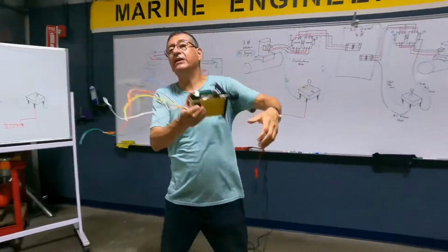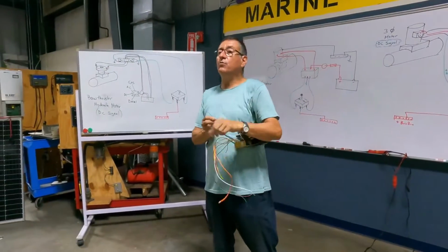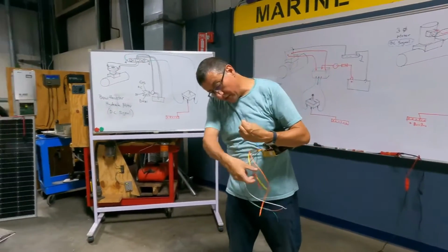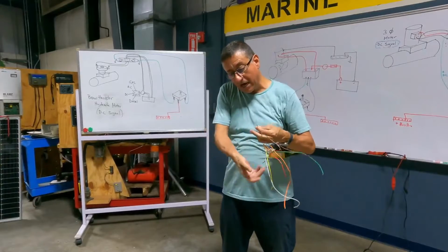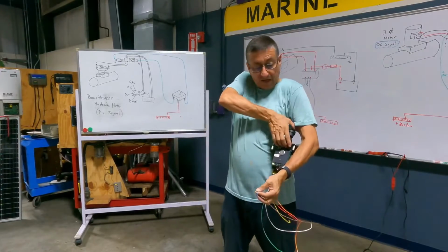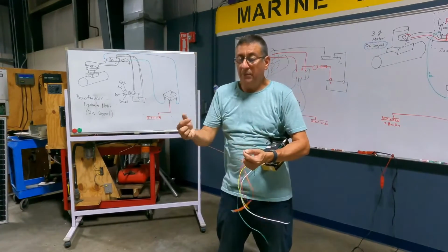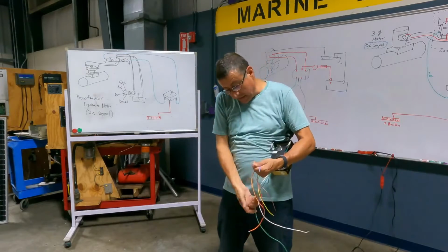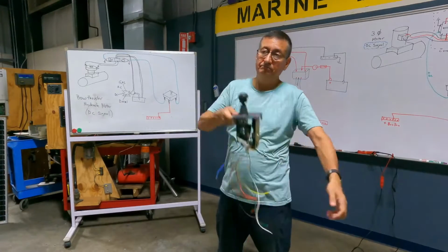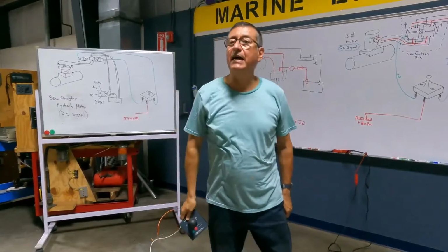I remove the power in the joystick. I identify which one is the common, which one is the output, and which one is the other output. And I check. Moving in starboard side, beep. Moving in port side, no beep. Replace that. Simple.